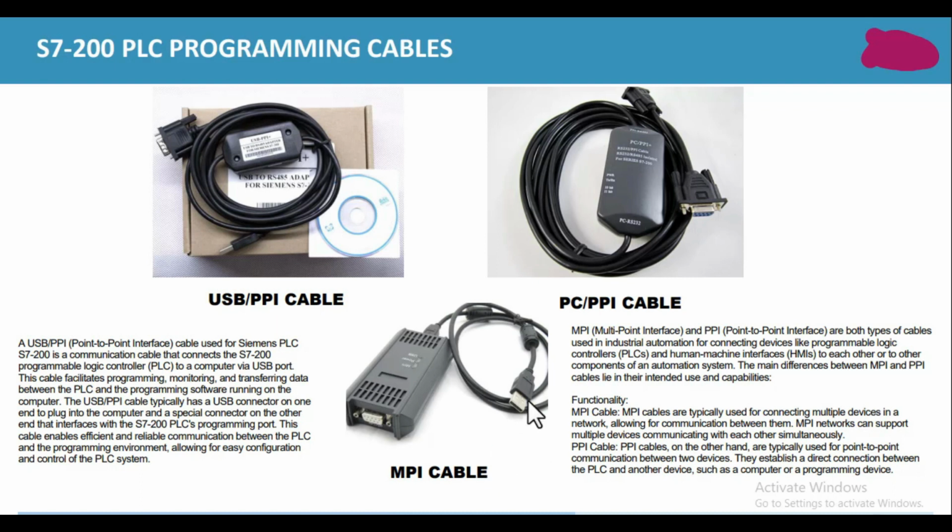Now we will discuss the difference between the PPI and MPI cables. MPI is multi-point interface and PPI is the point-to-point interface. The USB cable and the PC cables, these are the point-to-point interface cables. And this is the multiple point interface cable, which is MPI.